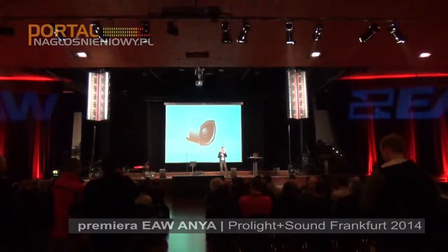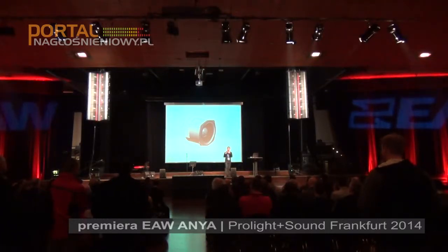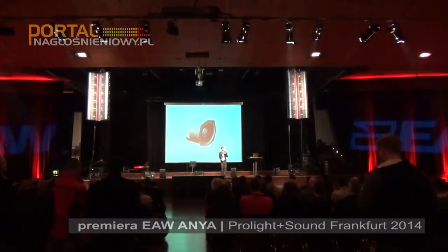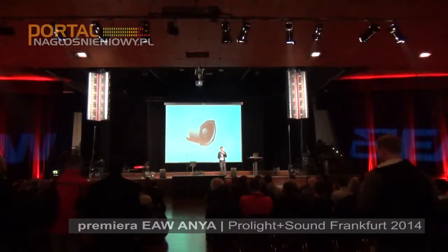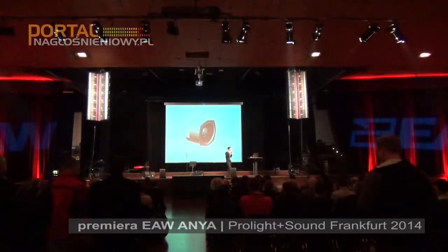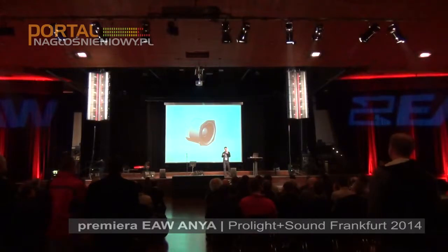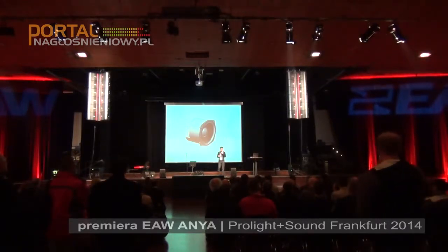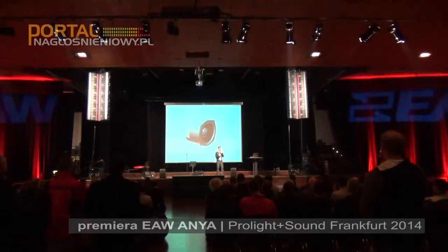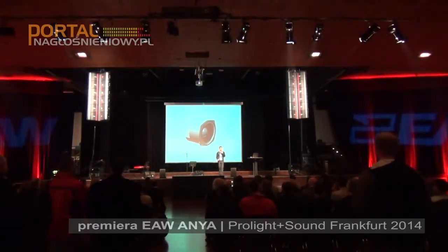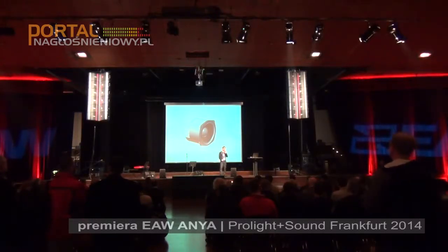We chose a 5-inch device because, like the high-frequency section, we wanted to get these devices as close together as possible, giving us that ability to operate and manipulate these devices over their entire operating range. Lastly, the rear can, the enclosure on the back of this device, gives us optimal air volume for that mid-frequency transducer, and also provides quite a bit of additional thermal mass and heat sinking, giving us the ability to remove more heat and improve power handling for improved output capability.